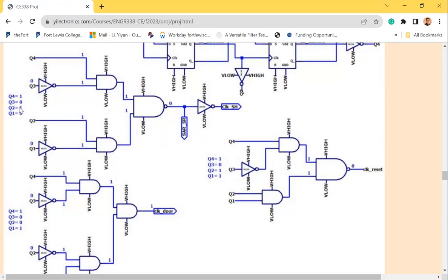So it seems like at the 9th cycle, I send it out, and at the 10th cycle, I'm using a zero active signal over here to set the SAR again to make it ready for the next, which is reasonable, right? The data is ready, I kick it out, then I just reset it for the next at the 10th. So that's the SAR set and reset.